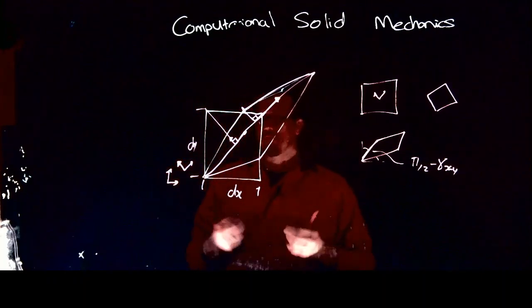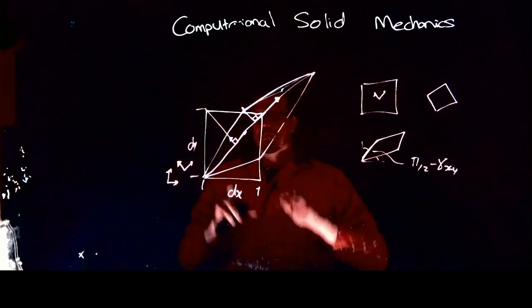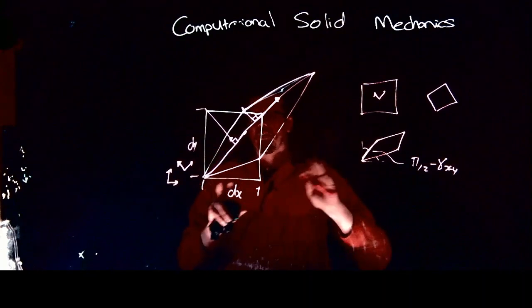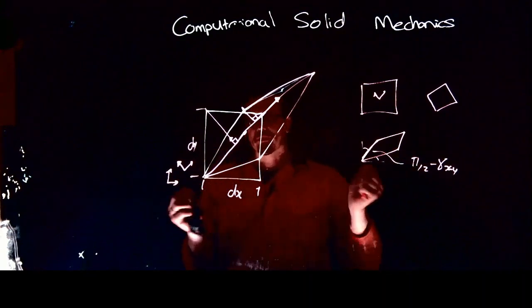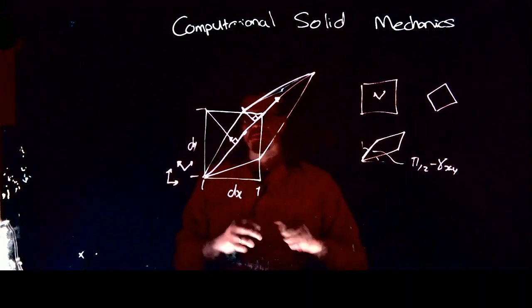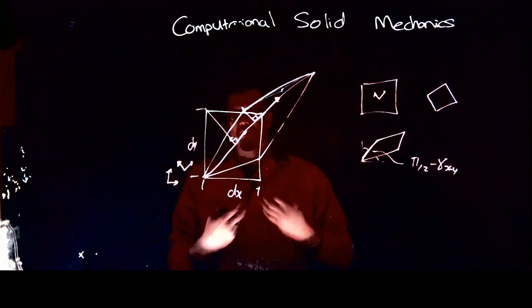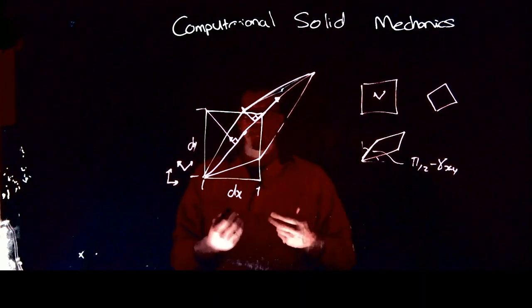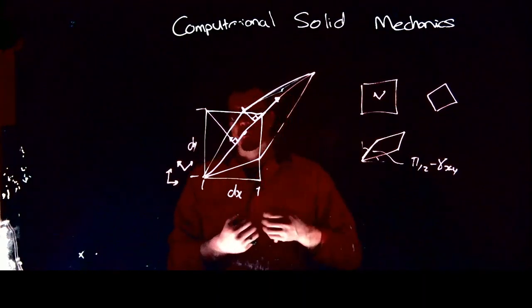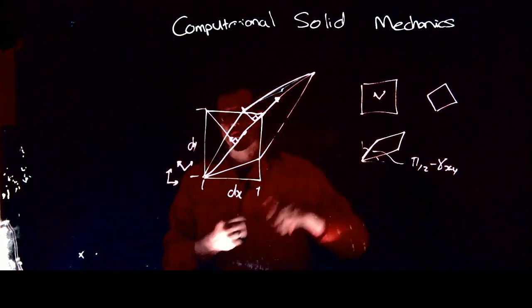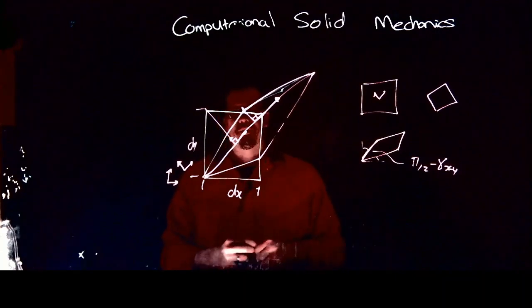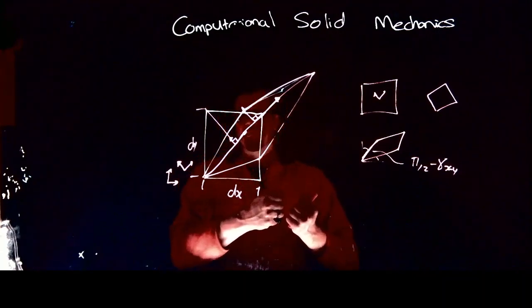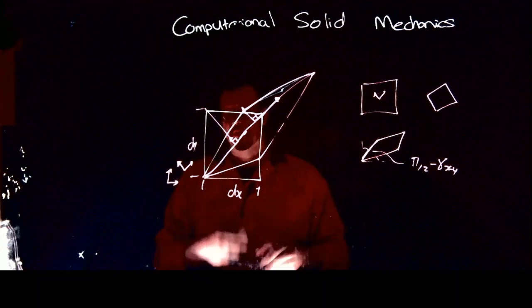The importance of this is that when we think about tensile stress and strain, compressive strains, or shear strains, it's really a function of the coordinate system in which we express them. There's a way of looking at it that will maximize the tensile strains that we'll see, and there's a way of looking at it that will maximize the shear strains that we might see.